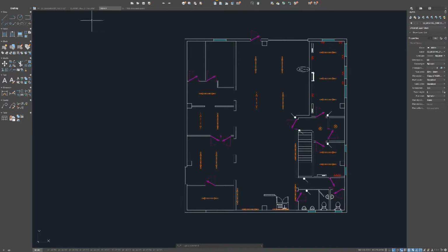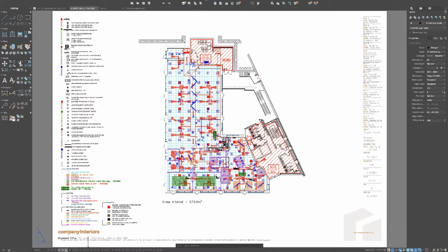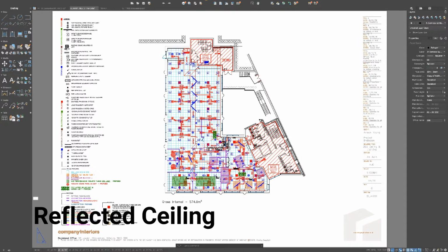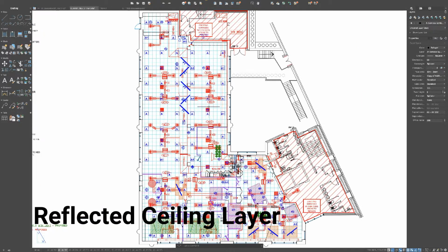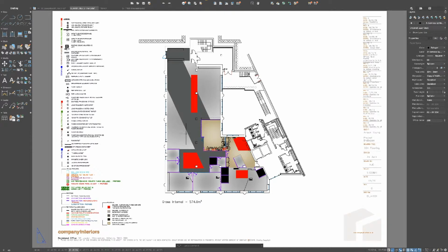That is why we go through that two-step process. Survey it, put it in the notepad, scale it out on paper, and then come back and put it through the system from here. So other drawings that would start, and as we get into more detail about those layers, here we would start with the small power or underfloor, building up through reflected ceiling layout. This is all our mechanical installations that we can see here. Keep on going. Flooring layout.